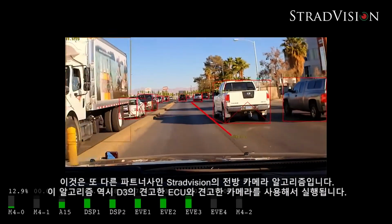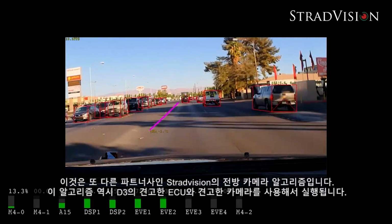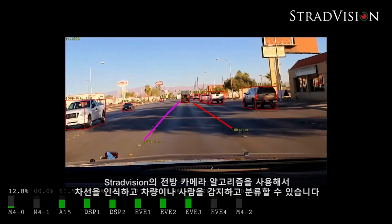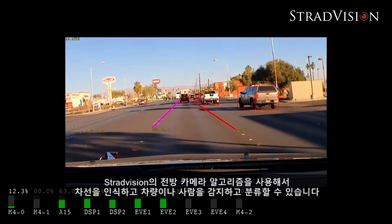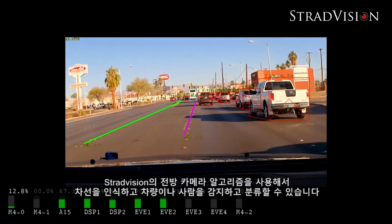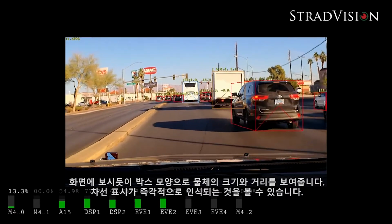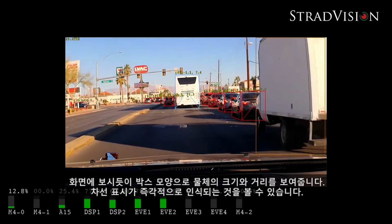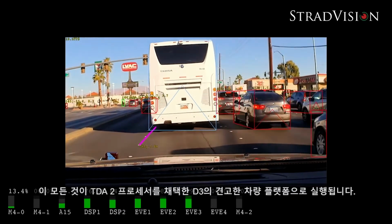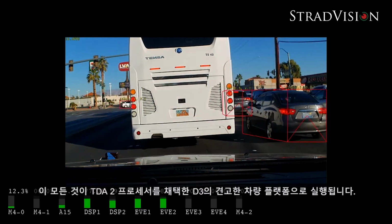This is a forward camera algorithm from one of our partners, StradVision. Again, this runs on a D3 rugged ECU using some of our ruggedized cameras. Our algorithm partner StradVision, again, provides forward camera algorithms. They're doing lane detection. They're doing object detection of vehicles, people, classification. As you can see on the graphics, the boxes tell you the size of the object, distance to object. You can see the lane markers come up live. And this is running on a TDA2 processor in a rugged on-vehicle platform available from D3.